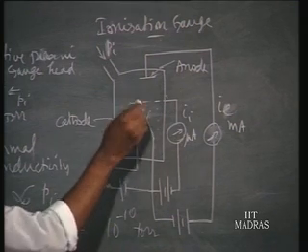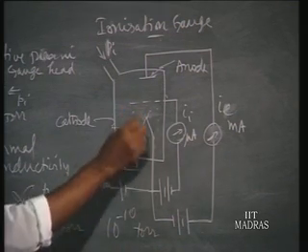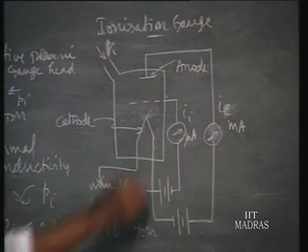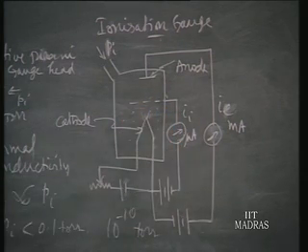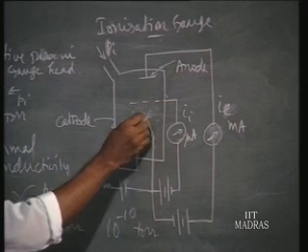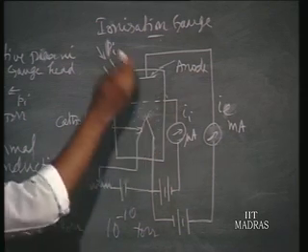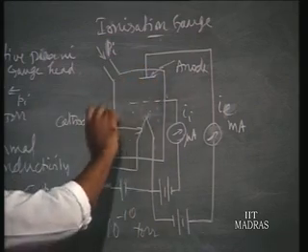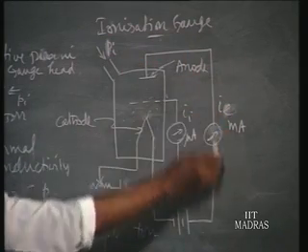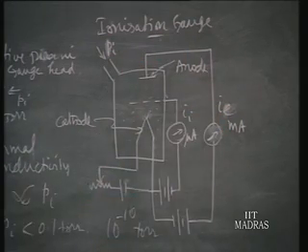The positively charged ions are attracted by the grid, which is negatively charged with reference to the cathode, and there is a current flow through the grid circuit in terms of microamps. The negatively charged ions travel with the other electrons and form a very small part of it, and are attracted by the anode, going through this circuit as the current IE.